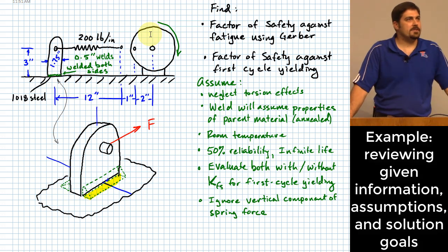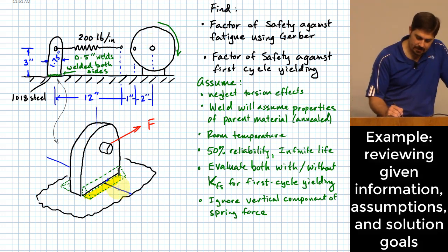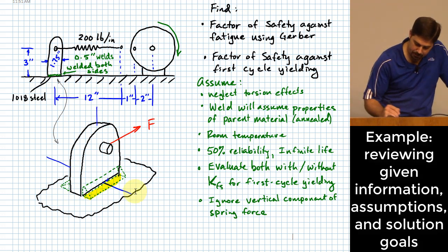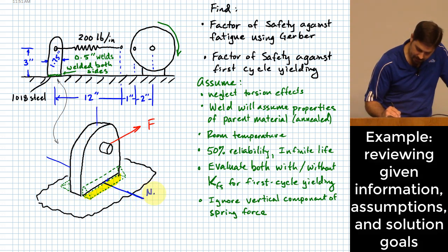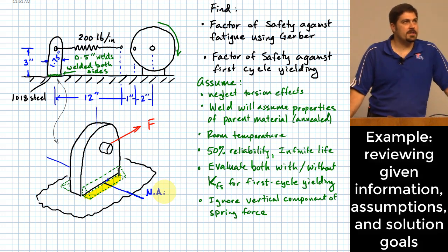What do you think that means? Okay. Yeah, so we're assuming, based on the dimensions of this shape, that primarily the type of stress that we're inducing in the weld is due to kind of a flexure around this blue line that I'm showing right here, which is the neutral axis. Okay, so this little line right here, that is the neutral axis. With respect to bending, we're saying that primarily the stresses that are induced are due to, I would say, bending as well as maybe direct shear, primary shear that happens in that weld group.